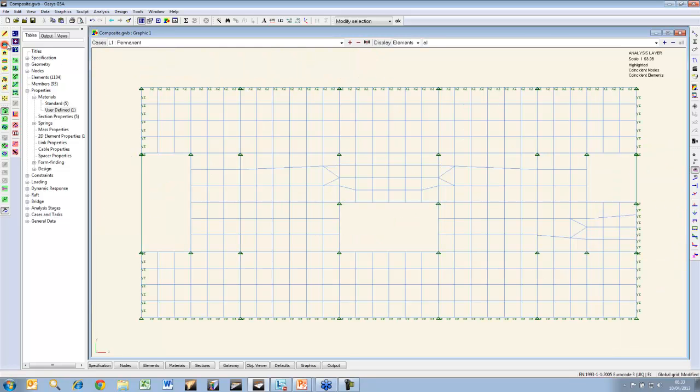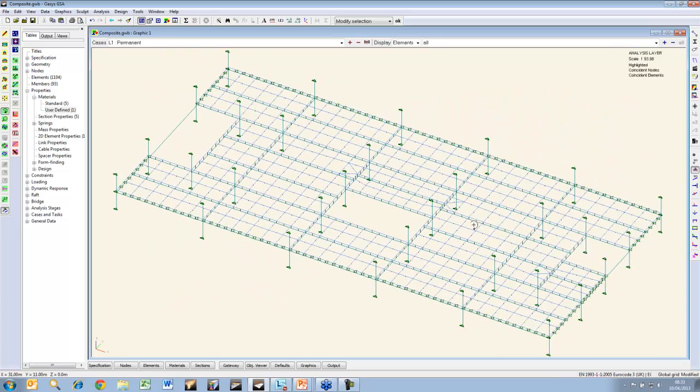Now, you could model these edge nodes purely as pins, and that will eliminate all horizontal vibration, which we could do. I'm going to leave these in line, and we might get a little bit of horizontal vibration, but the horizontal aspects will be ignored in the footfall calculations anyway. We've also got some service voids, which I've not modelled any restraints around. So let's do some analysis now.